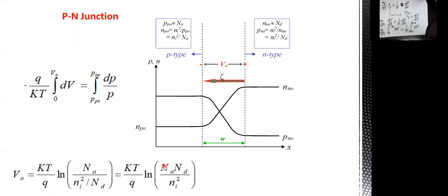Similarly, if you have a silicon p-n junction but you change the doping level, I mean NA and ND, then it will also change. Again, if you have a silicon p-n junction with a certain fixed doping, but you change the temperature, then you should expect a change in the overall built-in potential. So this is a very, very important equation, my dear students. You should know it well. Again, I'm not going to ask you about the derivation, but you should understand this equation well, and you can substitute to calculate the built-in potential for different p-n junctions.